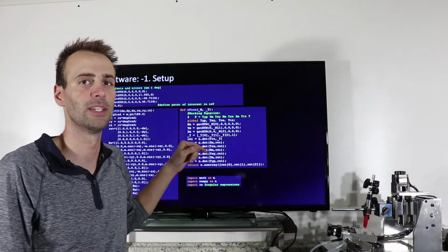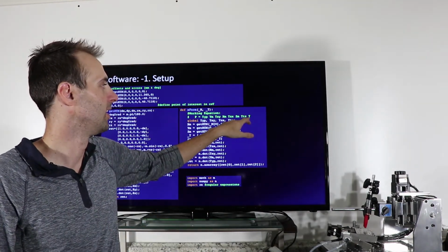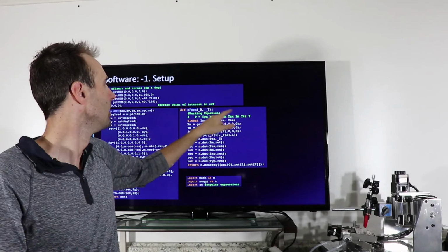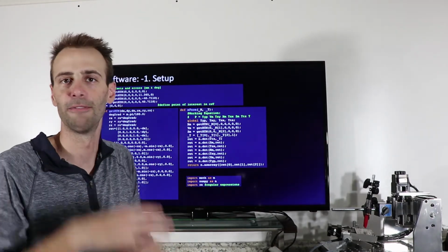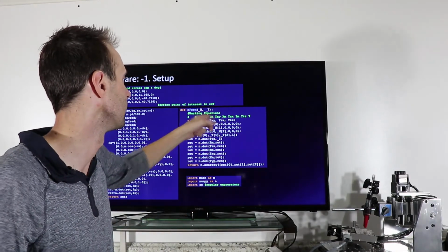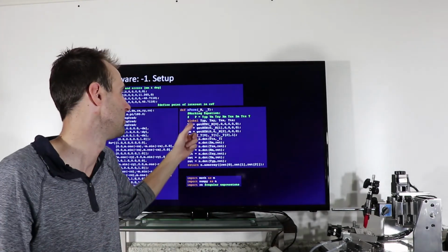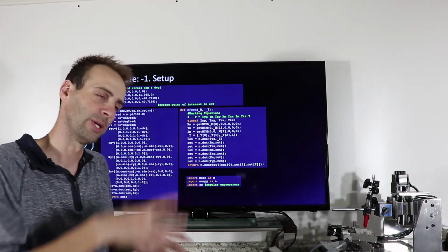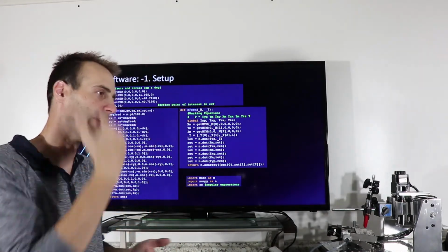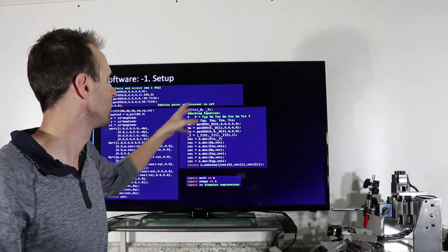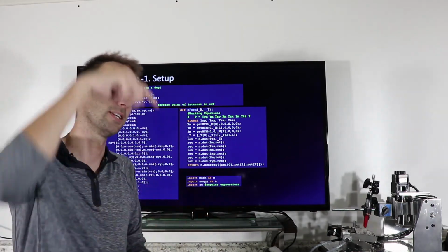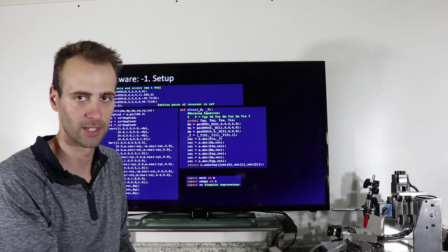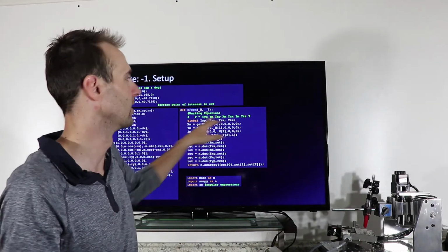So this tells me where my tool point is in part coordinates, given wherever my machine is. At machine home, this should be 0. But as you start moving the axes around, it won't be. So you tell it where the machine is, and it tells you where the tool tip is in part coordinates, using the kinematic chain.